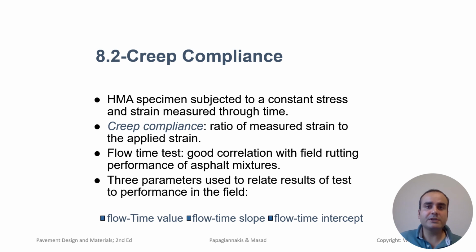Creep compliance measures the time-dependent deformation of asphalt mixtures under constant stress, providing insights into the material's ability to resist permanent deformation. Mixtures with lower creep compliance are stiffer and less likely to rut under sustained loads, making them suitable for areas with heavy traffic. Creep testing helps evaluate how the mixture will perform under long-term loading conditions, particularly in hot climates.